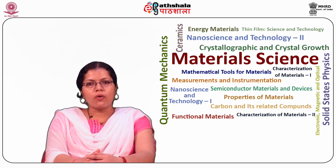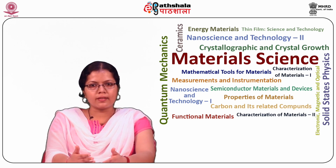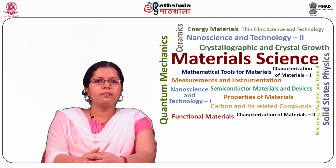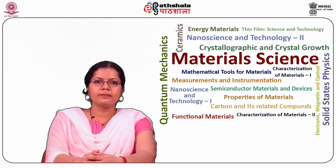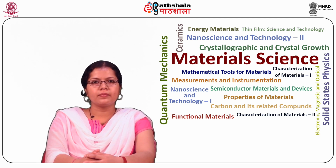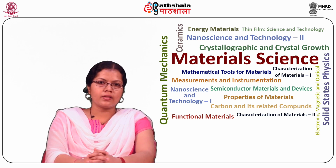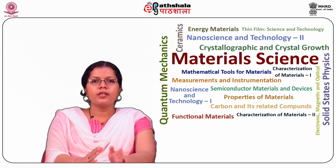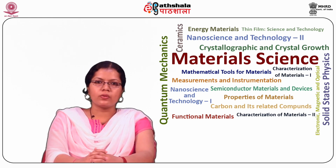Since the current of the moving coil is carried by the instrument springs, it is limited to values which can be carried by springs without appreciable heating. A series resistor is used in the voltage circuit and the current limited to a small value, usually between 10 to 50 milliamperes.